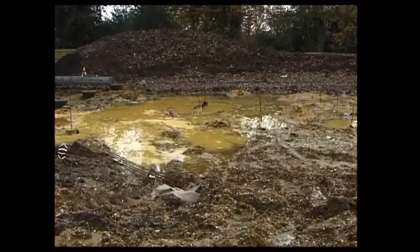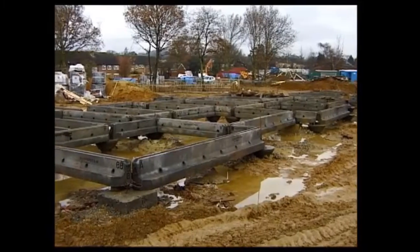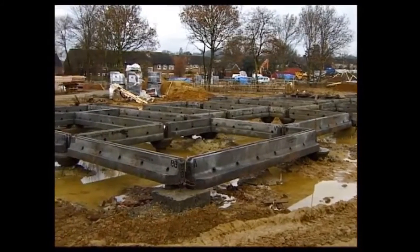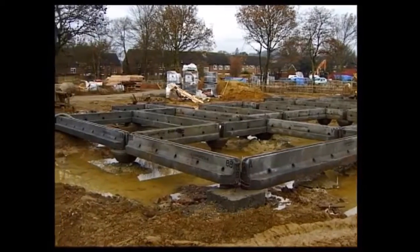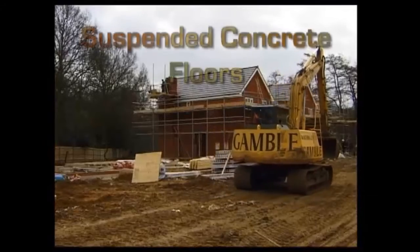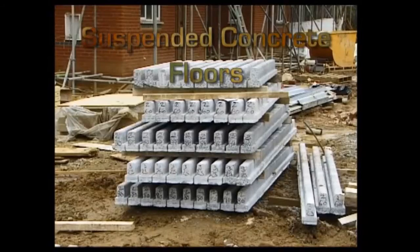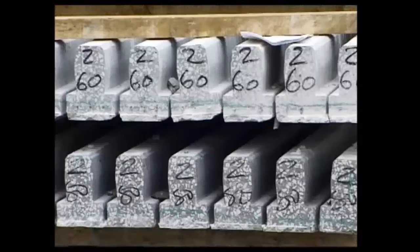Where groundwater levels are high, traditional DPMs will not be adequate. Most DPMs are designed to prevent capillary action, not direct water pressure. High groundwater levels can also increase the risk of chemical attack, especially if the slab remains wet for long periods. In all these situations, it's preferable to use a suspended concrete floor, and nowadays most suspended floors are precast.